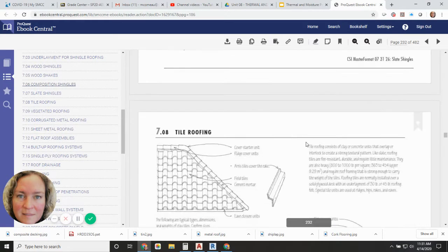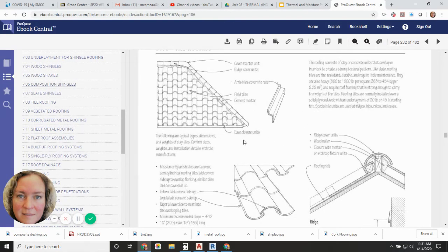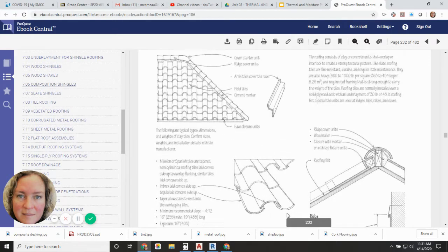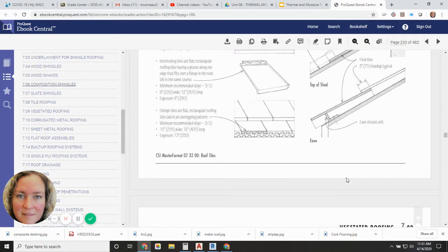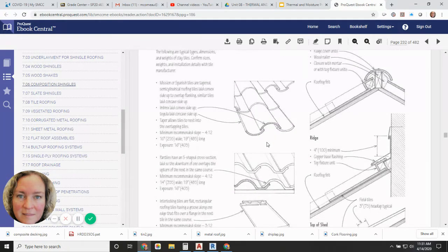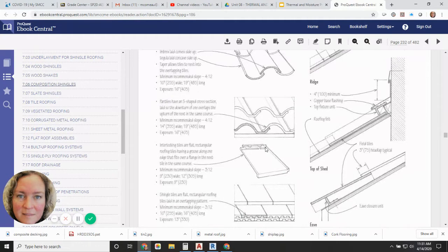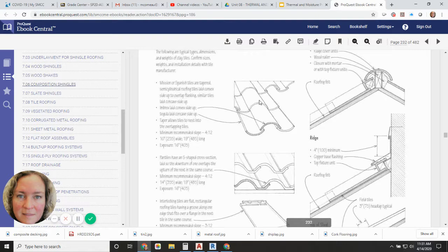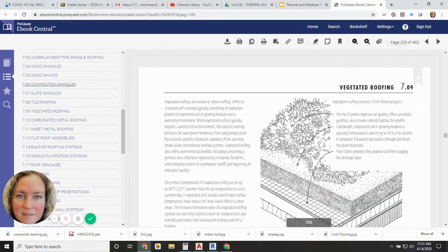And then just different configurations. These are Spanish tile. And similar to a shingle, they last a pretty long time too. Just a single tile can be replaced. Really easy to maintain, but not great in the snow. They can deteriorate, crack, and in our area too, because we throw a lot of sand around in Maine, and we live by the ocean. These can deteriorate a little faster too.